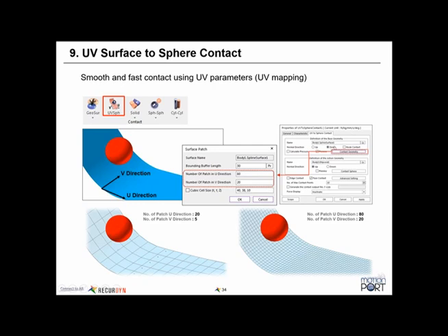Sometimes, with these other contacts, it's changing the resolution of the contact patches according to factors that you can control, other factors related to curvature and so forth. Things like the plane tolerance factor are an example of that.